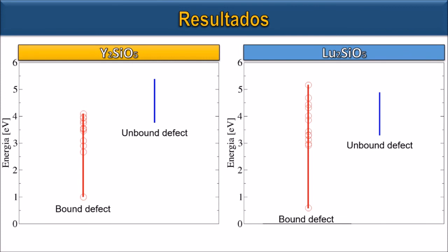For this type of defect, in case these point defects, oxygen vacancies and interstitial oxygens, interact in the structure, which are called bound defects, most of the energies found are smaller than that obtained for the unbound condition, meaning that the close proximity of the interstitial to the vacancy reduces the total energetic cost due to the Coulomb interaction between the effectively charged defects.